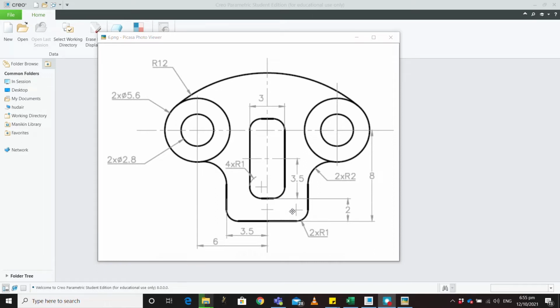The other thing you can note is a good convention, which is highly regarded in engineering drawings or CAD drawings, is to start dimensions from the same point. For example, from this point to this point is 2, and this to this is 8. You could have given it from here to here as 6, but giving it in different places at different lines is not considered good practice.